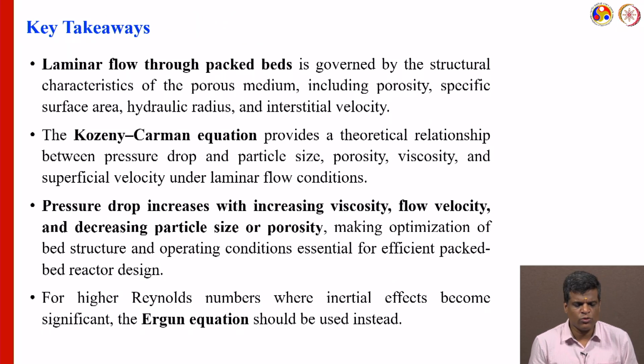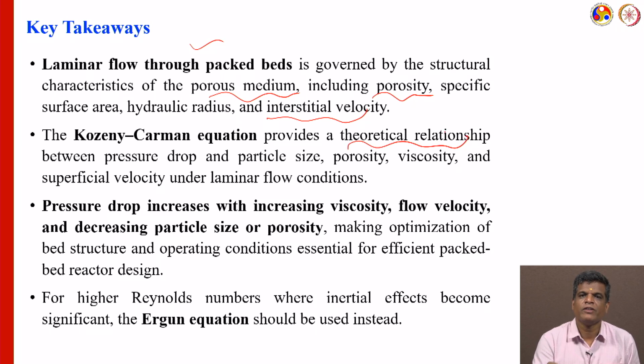So what are the key takeaways today about laminar flow through packed beds? It is governed by the structural characteristics of the porous medium. We discussed the porosity, specific surface area, hydraulic radius and interstitial velocity. We discussed the Kozeny Carman equation, which gives the theoretical relationship between the pressure drop, particle size, porosity epsilon, viscosity mu, and superficial velocity under laminar flow conditions.